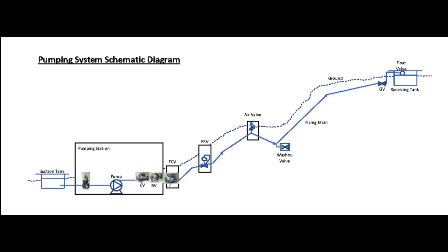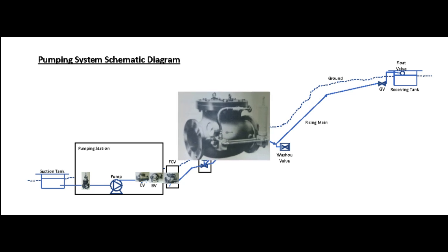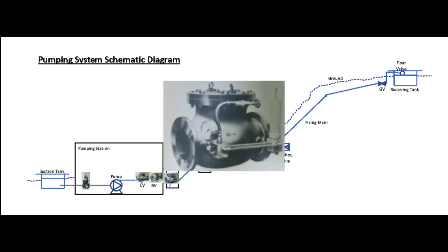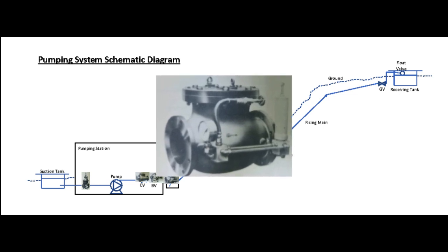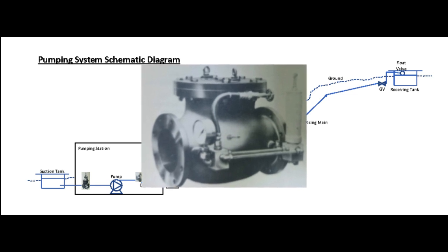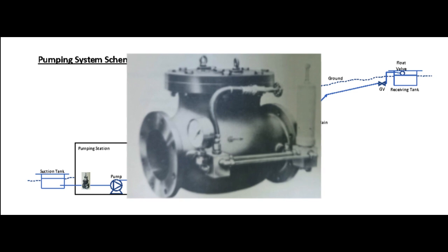Flow control valve. This valve is installed at the common header or rising main where a specific volumetric flow is required to be delivered to the system. An accurate flow can be achieved by using this valve as compared with the butterfly valve. There are many types of flow control valves in the market, where the valve functions based on pressure, movement profile, functionality and actuating medium for a pumping application. Careful selection is required for flow control valve application.